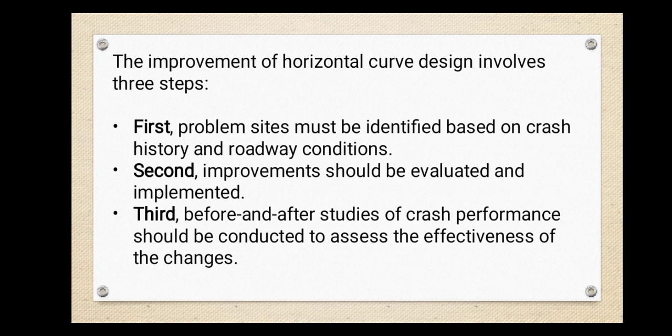The improvement of horizontal curve design involves 3 steps. First, problem sites must be identified based on crash history and roadway conditions. Second, improvements should be evaluated and implemented. Third, before and after studies of crash performance should be conducted to assess the effectiveness of the changes.